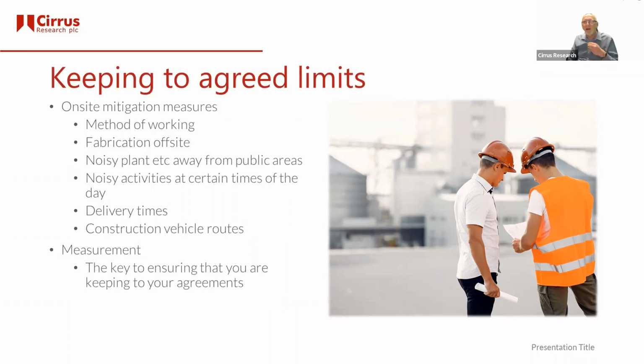So there are lots of on-site mitigation measures that people can use: different methods of working, fabricating as much as possible off-site, keeping noisy plant away from any public areas, limiting the really noisy activities. Sometimes you've got pile driving and things like that.